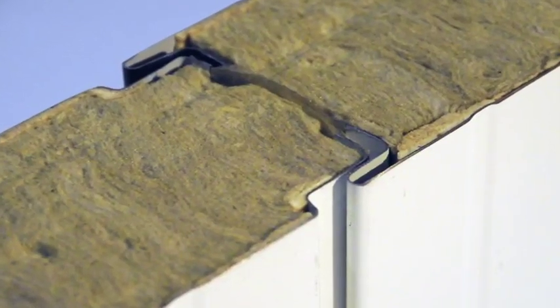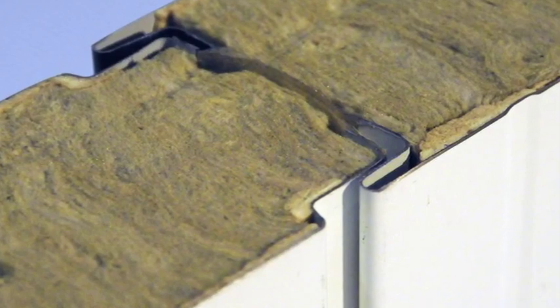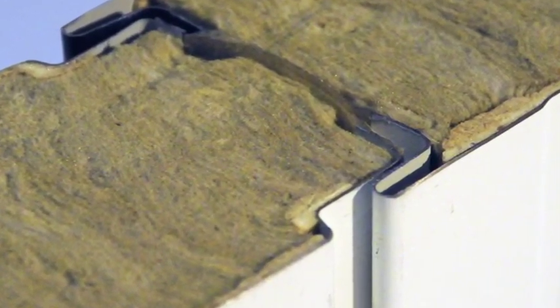Mineral wool panel. The lamellas are adhesively bonded to the two metal surfaces. It's used for walls, external walls of buildings. It's also used internally for walls, ceilings, and it has been used from time to time in cold stores, although that application is much reduced. Mineral wool panels represent about 5% of panels in use in the marketplace at the moment.